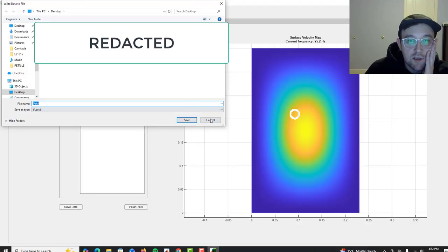So I think it saves the SPL, the on-axis SPL, the velocity, and the impedance in an Excel spreadsheet or a CSV that you can use in Excel. And if you don't enter in a name here, which I think was the default for a while, the program will make an error sound. So just make sure that you enter in a name.